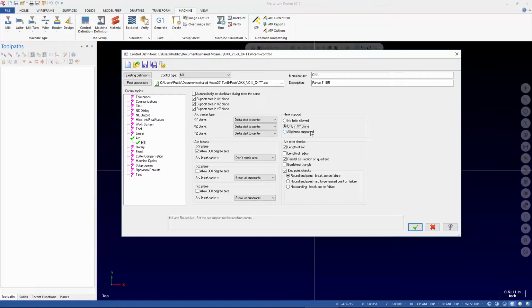So, do tilted planes output as if XY? Yes. Tilted work plane does that, and that's the whole point, that it allows you to do cutter comp. It allows you to use regular planes, and it uses canned cycles.